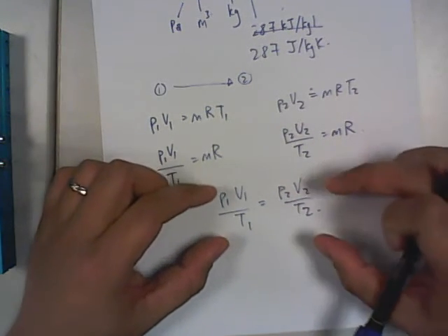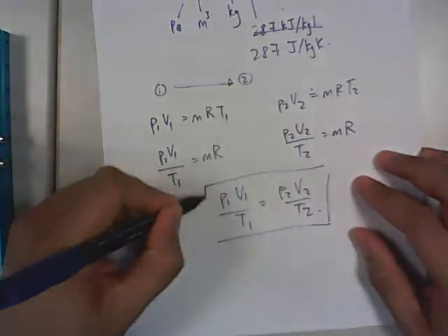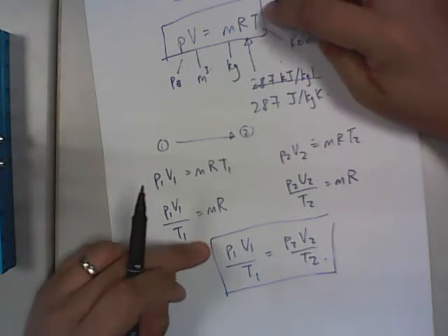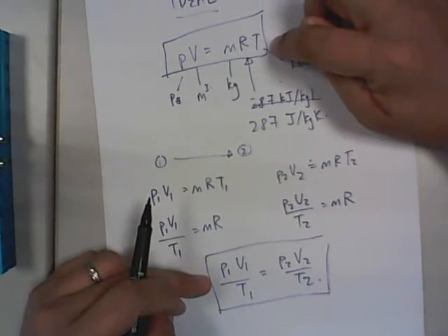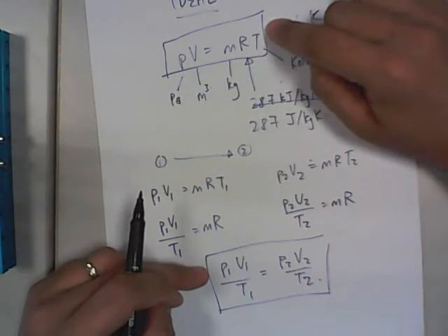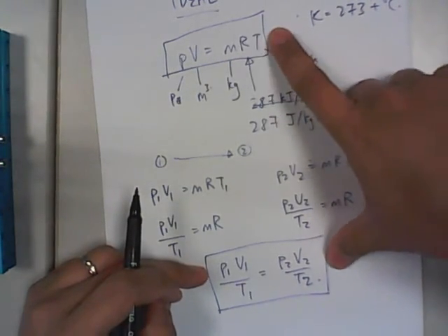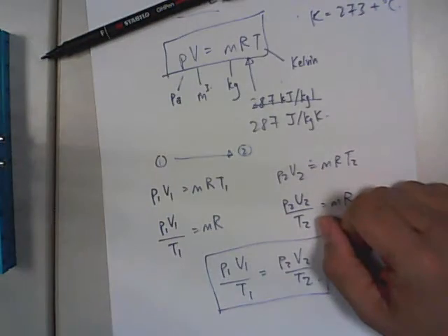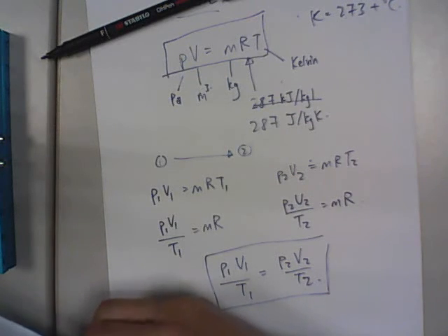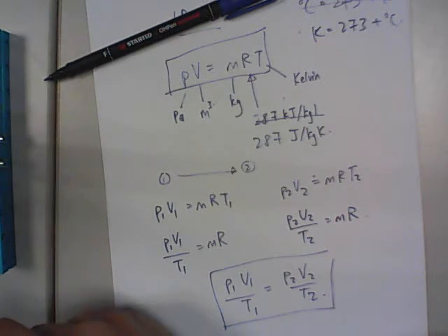So with this, a lot of this is the basis of what comes out from the perfect gas characteristic equation. These two equations apply no matter which kind of process you are looking at. We have 5 main processes. Later we will talk more about this, but what we are saying here is that no matter which process it is, these two equations will not go wrong. If we are talking about ideal gas, don't be mixed up with steam. Steam has a totally different treatment, and steam will not have this perfect gas characteristic equation.